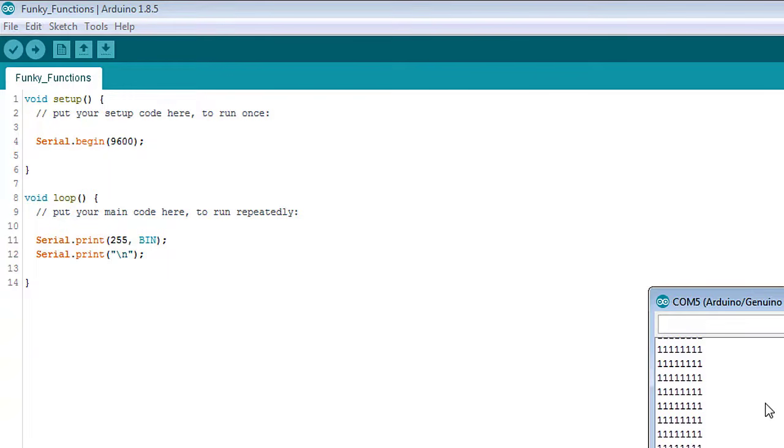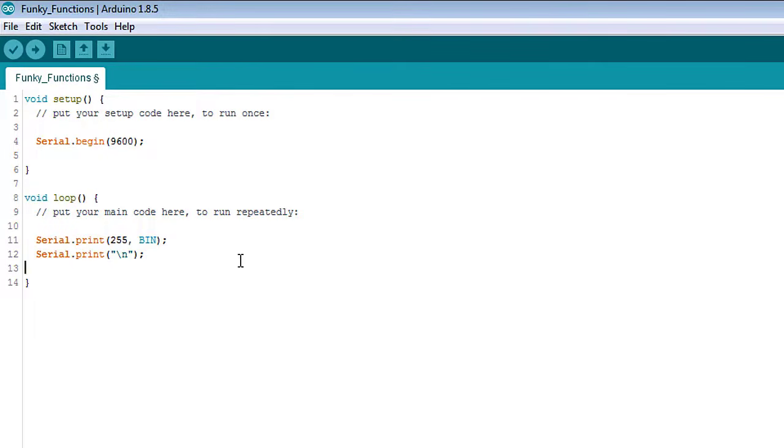Next, we see this particular function, the Serial.print function, has two parts with a period or dot in between them. Not all functions in Arduino are like this, like the delay function, which just looks like this. And I'm just going to comment it here. You put a value in here, a number of some sort, and it's just one part. So not all functions in Arduino have two parts, but many of them do.